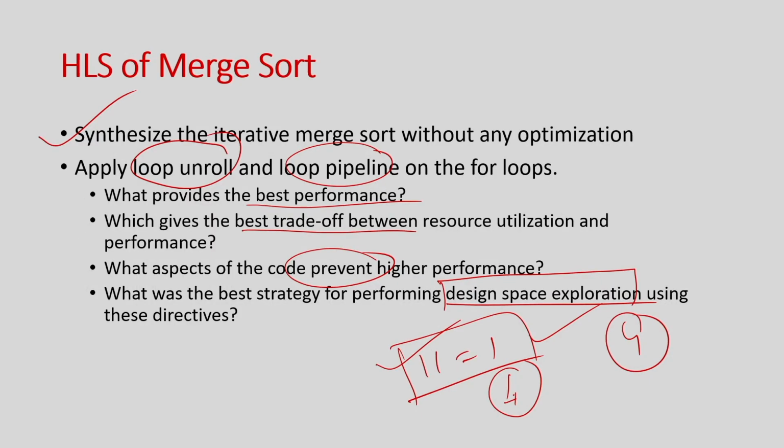The second thing is memory access, and you remember I have already discussed that once you map this array, it will be mapped to block RAM in the hardware. One of the challenges in developing hardware is that this block RAM has limited ports, right. At most 1 or 2 ports are there, so whenever there are more than 2 accesses to an array in the loop, it will take multiple cycles just to read those elements, and that might create a problem in getting an initiation interval of 1, or basically getting the maximum performance benefit from the pipelining.